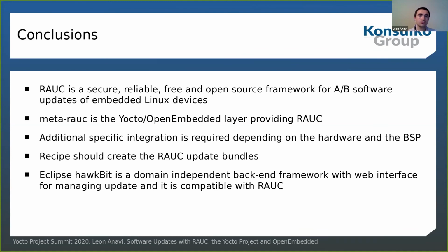One of the things that you should have in mind is that if you are using rauc for a different target, not a Raspberry Pi, most probably you'll be using it for another device, you need to go through all these specific steps to integrate rauc for this device. This is the specific thing that you should go through: the steps that I've explained, and apply them for the device that you have.